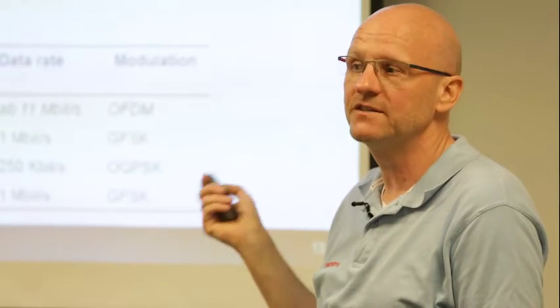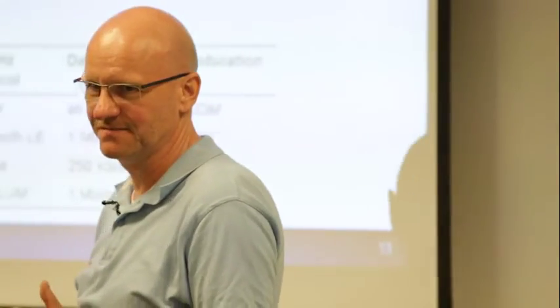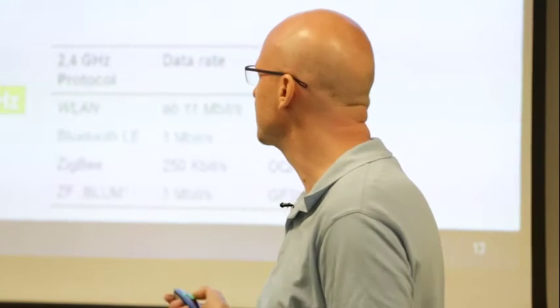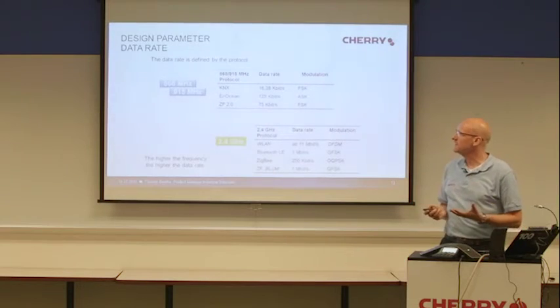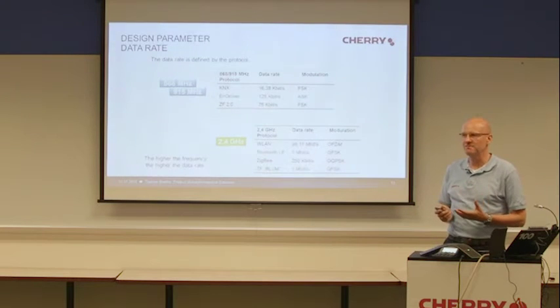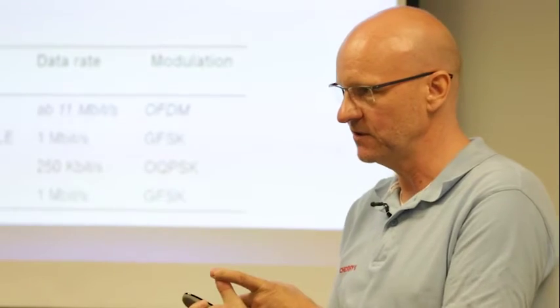And this is a great challenge for RF systems, because when you have a very low data rate, you need much more time for the system to send out data. And time means energy for an energy harvesting system. We will see it later. So you see, data rate is a very, very important parameter for us. And data rate is combined with the protocol.